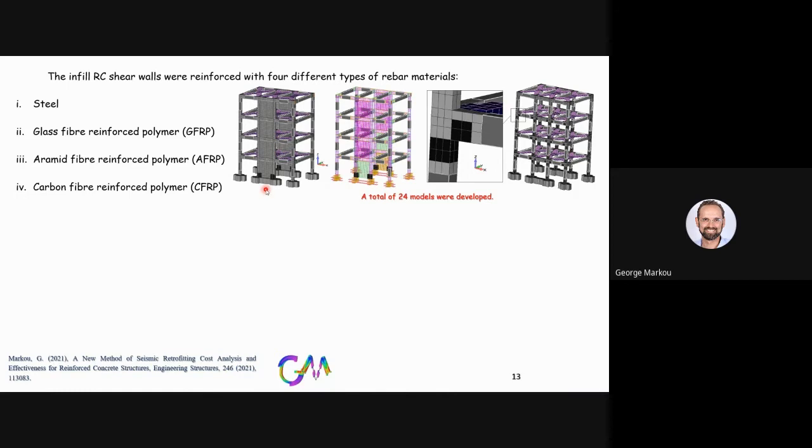And a model was developed in order to capture the experimental results. They applied 3 different rounds of cyclic loading, 0.1 G, 0.25 G, and the final set was, they called them the funeral cycles, given the fact that they pushed this specimen until it failed completely.